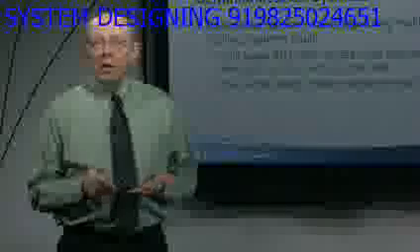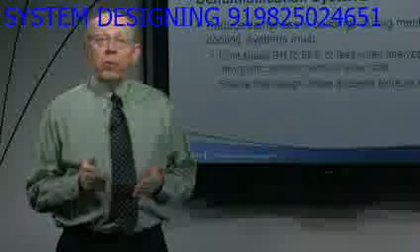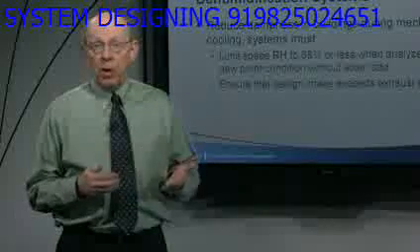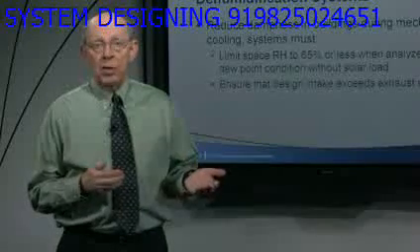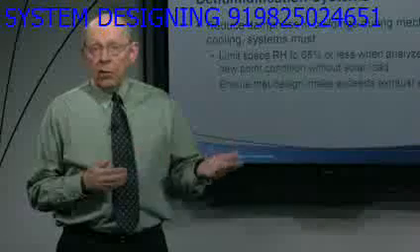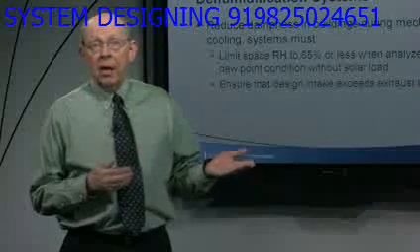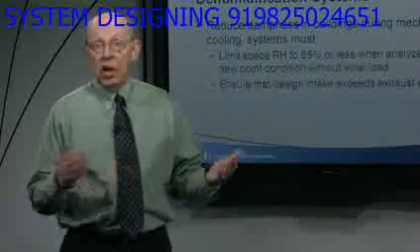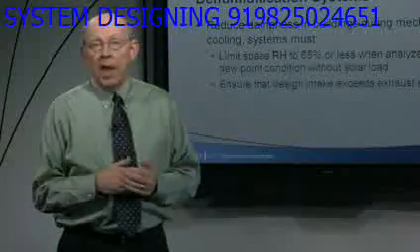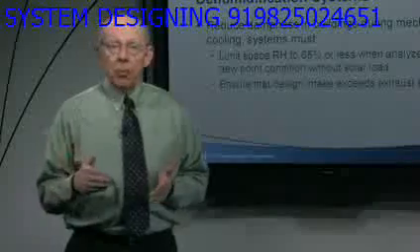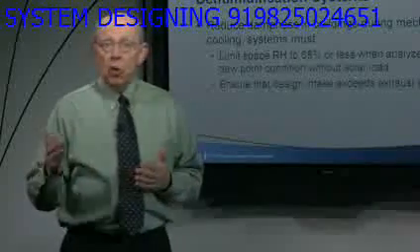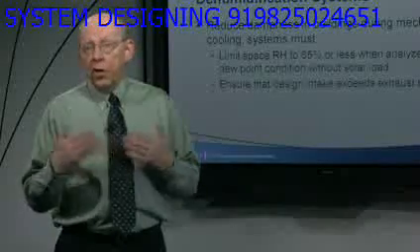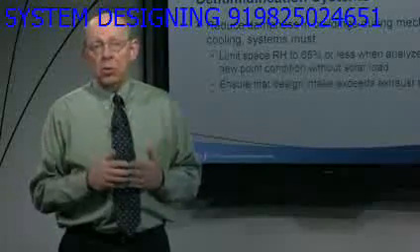Section 5.9 encourages dehumidification to prevent problems associated with damp buildings and positive building pressure during mechanical cooling operation. Relative humidity above 65% can lead to high water activity level in porous materials, which can lead to mold growth. And negative building pressure during cooling operation pulls moist outdoor air into the building envelope, which can lead to mold growth within the walls or in the occupied zones.